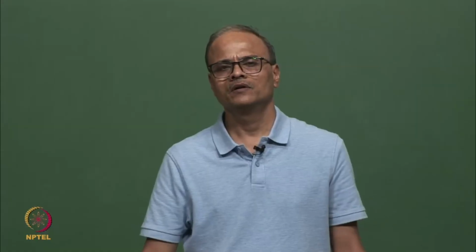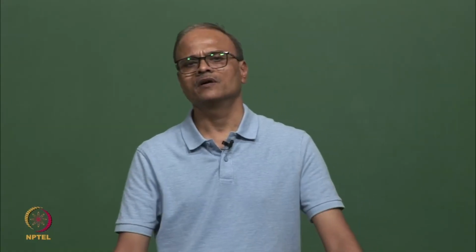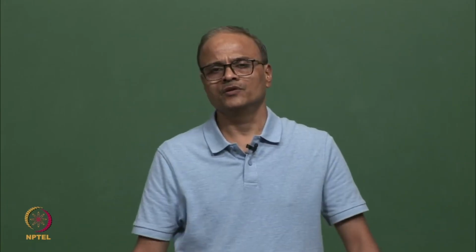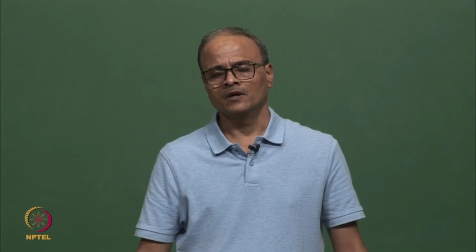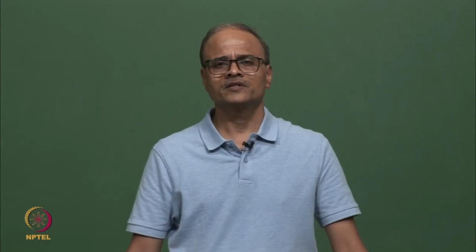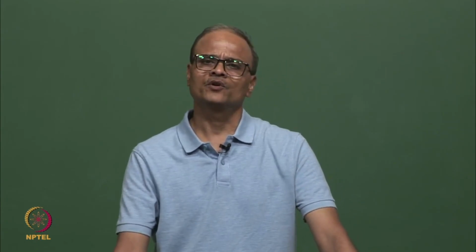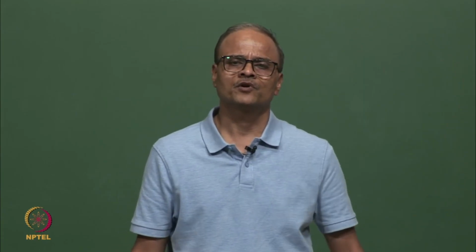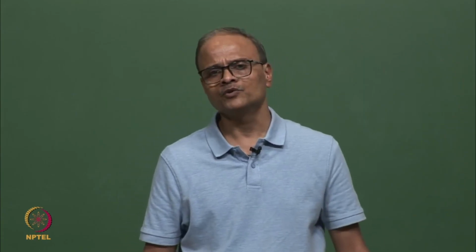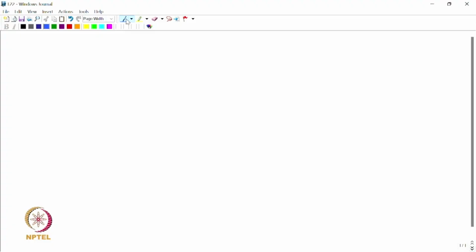Hello everyone, welcome to this lecture. In the previous lecture we studied excitation of a structure using impact hammer. The excitation will cause the structure to respond, and then the question is how do you measure the response of the structure. So in this lecture today we are going to talk about how to measure response, what response parameter should be used, and we are going to talk about accelerometers for response measurement.